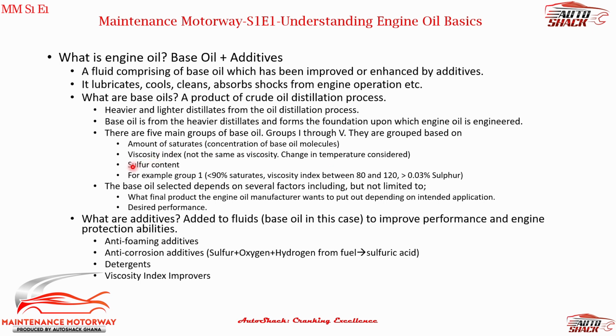Now sulfur is an undesirable factor because sulfur actually facilitates corrosion. The sulfur mixes with hydrogen in the fuel. The fuel is a hydrocarbon, and that also mixes with the oxygen in the engine, and that causes corrosion from sulfuric acid. Now remember, acid can be corrosive, and sulfuric acid is very, very corrosive.